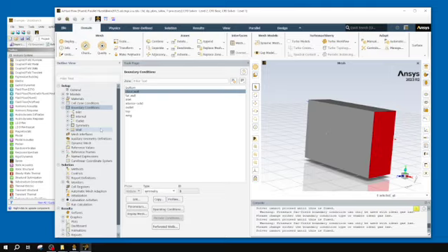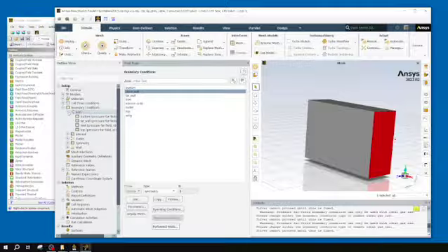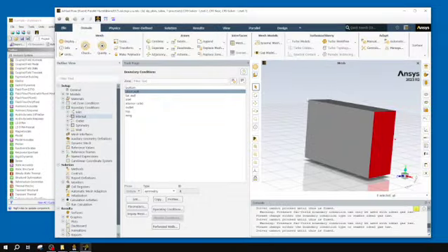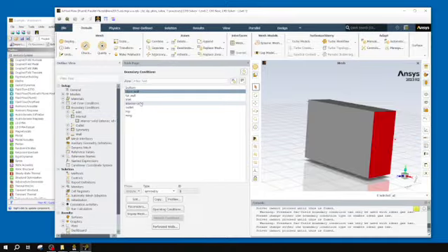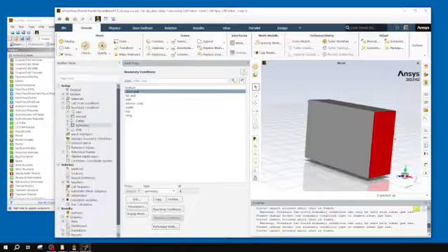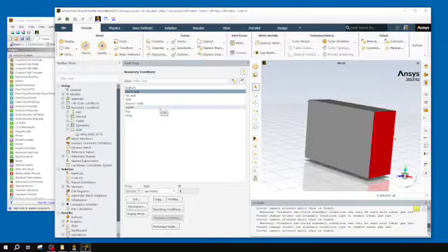So you can go through some of these. As you can see, all four of those walls I defined as a pressure far field are considered inlets. My internal was already defined. My outlet's that pressure outlet. And finally, I have that symmetry and a wall condition. I realize I didn't double check my wing. We do want your wing to be a wall.